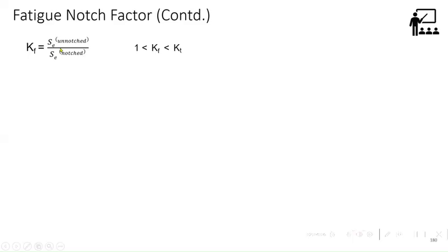So for the endurance limit, 10 to the power 6 you are taking as the endurance limit. Again, please remember, that is for ferrous materials at 10 to the power 6, but for non-ferrous you have to take the comparison at 5 into 10 to the power 8. In that case, the stress level will be less. But as usual, as a conservative choice, you can take 10 to the power 6. That's not wrong, but in practical sense, there is no endurance definition for non-ferrous material, and the benchmark is 5 into 10 to the power 8. So you should compare Kf not at 10 to the power 6 for aluminum, it is 5 into 10 to the power 8.